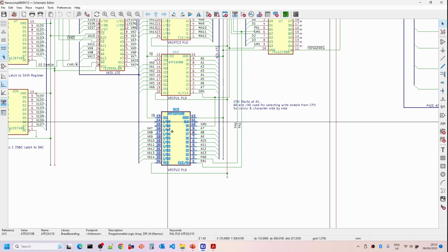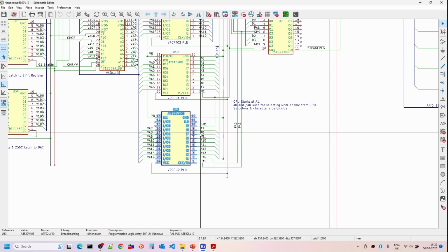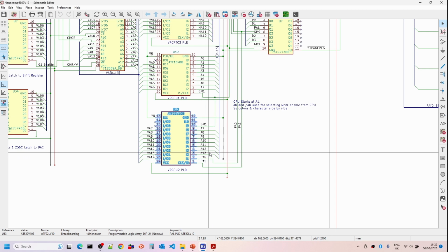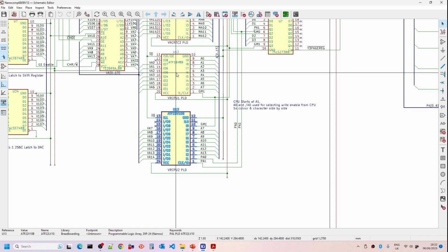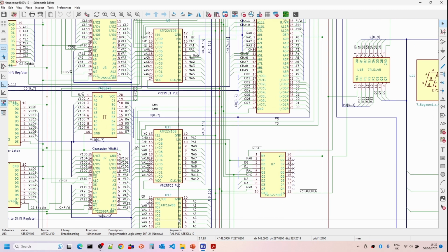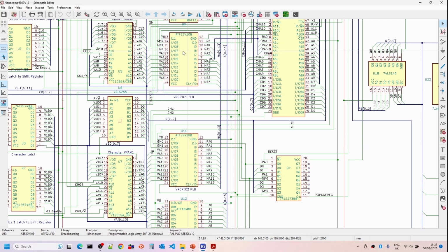And then down here we've got the same thing. So the input lines are going to be an amalgamation of the 3 modes, and then the GM1 is all that's needed to switch between the different configurations for the CPU, whereas for the CRTC we need to distinguish between the character mode and the 2 graphics modes because the mapping will be different. But once we put these changes in here and wired up the various pins here, we should be good then to be able to switch between character mode and the high-res graphics mode in software.